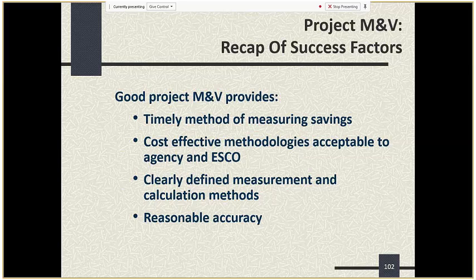So now, not only do you have a better control system, but you have a lot of the ancillary, I'll call it, control components in the field that have been upgraded and replaced so that they can actually function in response to control signals. That's true. Primarily what got replaced at H&L was a monitoring and a stop-start of fan systems to full DDC control, temperature control of the units.